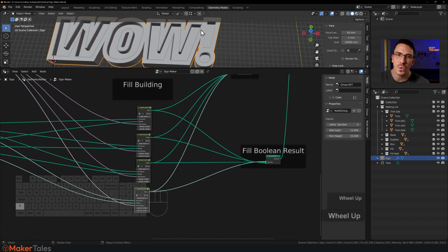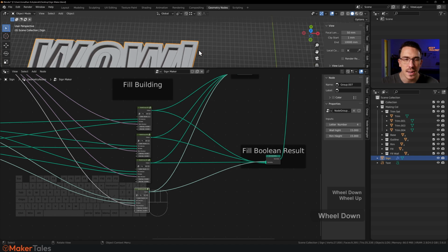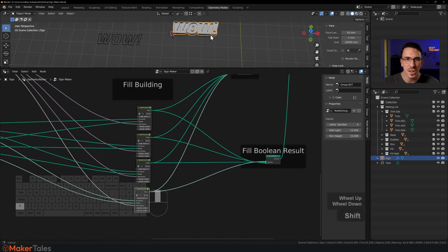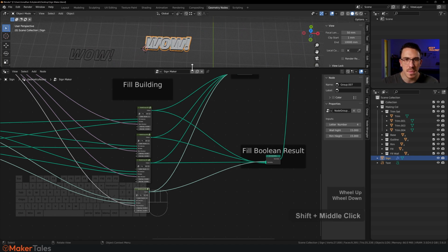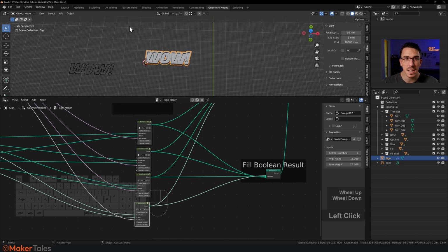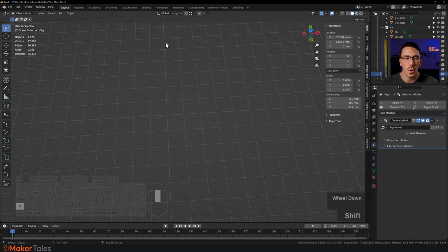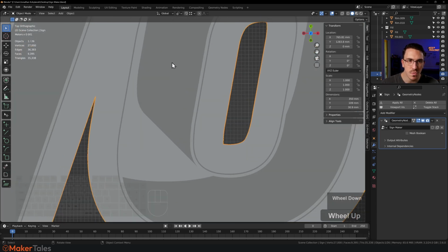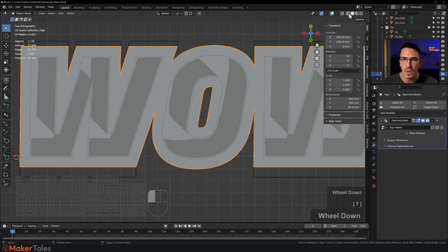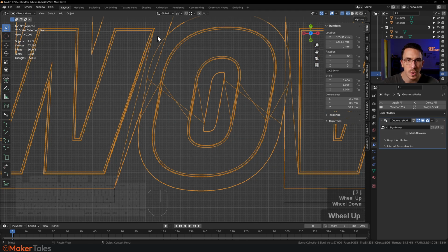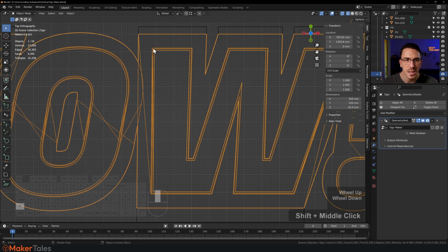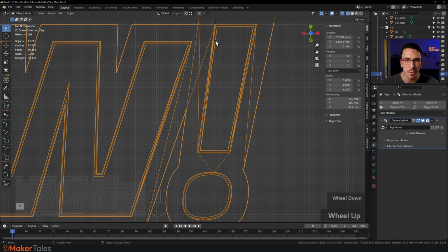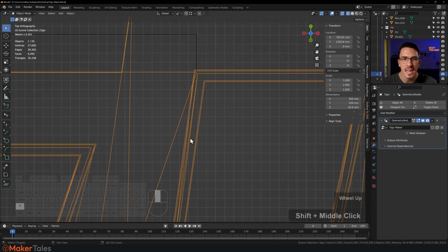Okay, now that we're at this point here, let's take a look at this mesh just quickly because it might have some issues. We should always inspect it before we go. What I'm mainly looking for is right at the point. So I'm going to go into my X-ray, right at the point here where it goes in, just making sure that there's no overlap. Look, right here. There we go. We've got a nice teeny tiny little overlap there.